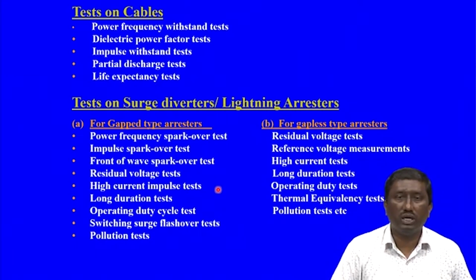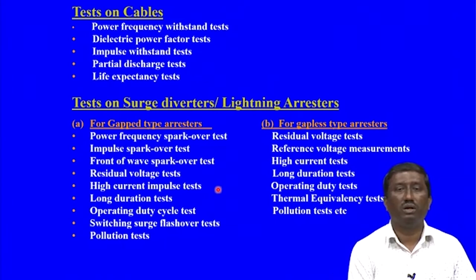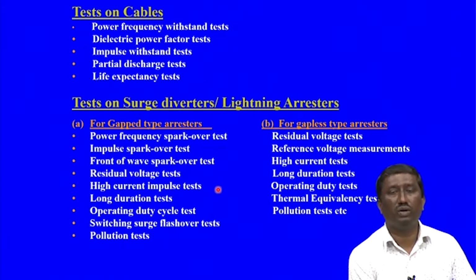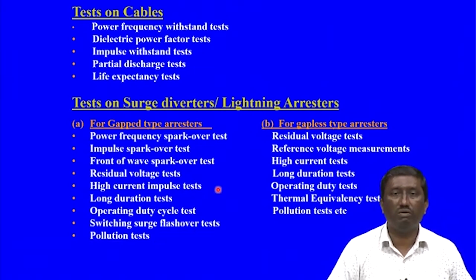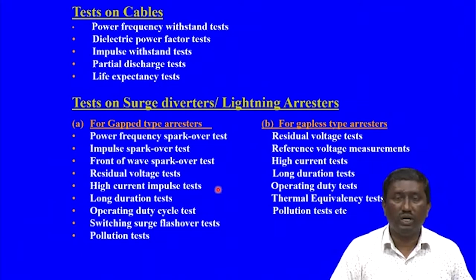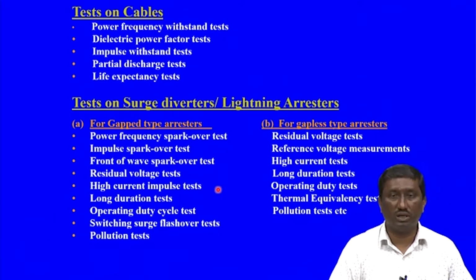So, long duration again depends on the transmission type of model where the inductor and capacitors are placed, and a rectangular waveform which we have discussed. The rectangular waveform simulation is being done over a period of time, say in terms of milliseconds, with a certain magnitude that has to be applied, and the performance of the arrestor has to be checked.